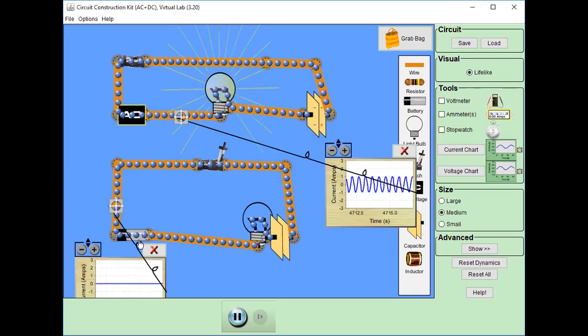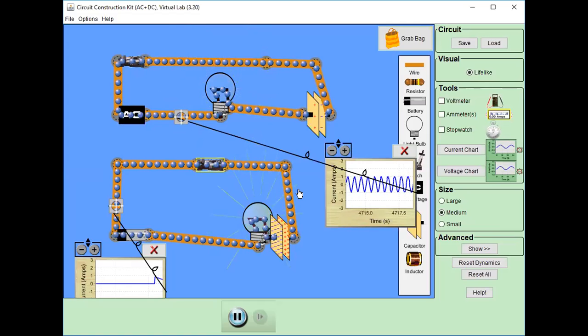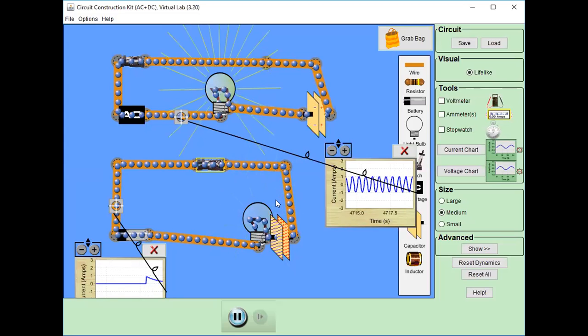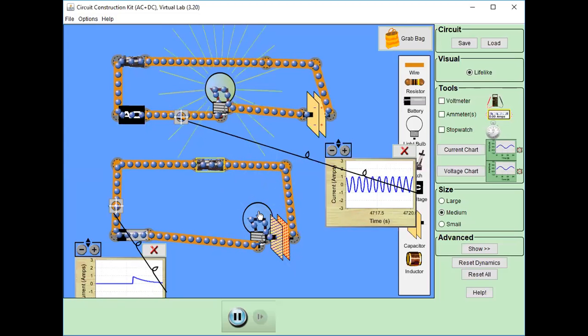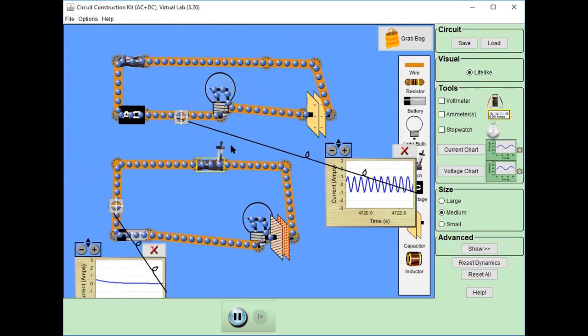All right, now here, this is a DC circuit. Okay, so let's watch that. Okay, so the bulb lights up, but it goes off at one point. Why is that? Look at this capacitor. It's fully charged, right? So that's why the current stopped flowing in the circuit. Again, let's open this. Nothing will happen. But here, look at this capacitor. It keeps charging, discharging, switching the direction. Charge, switch the direction, right? So that's why you see continuous flow of current here. But for this one, it's not. It stopped because the capacitor is fully charged now.